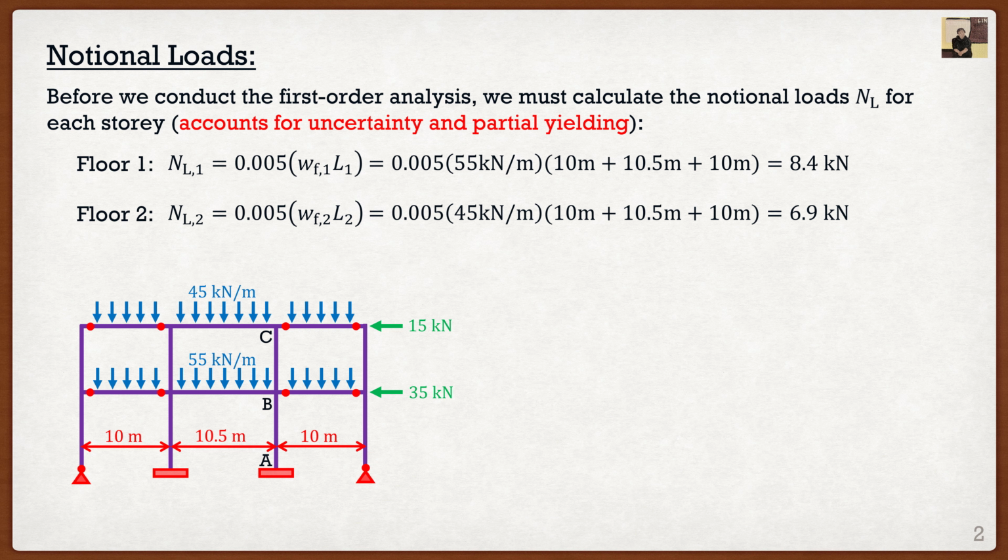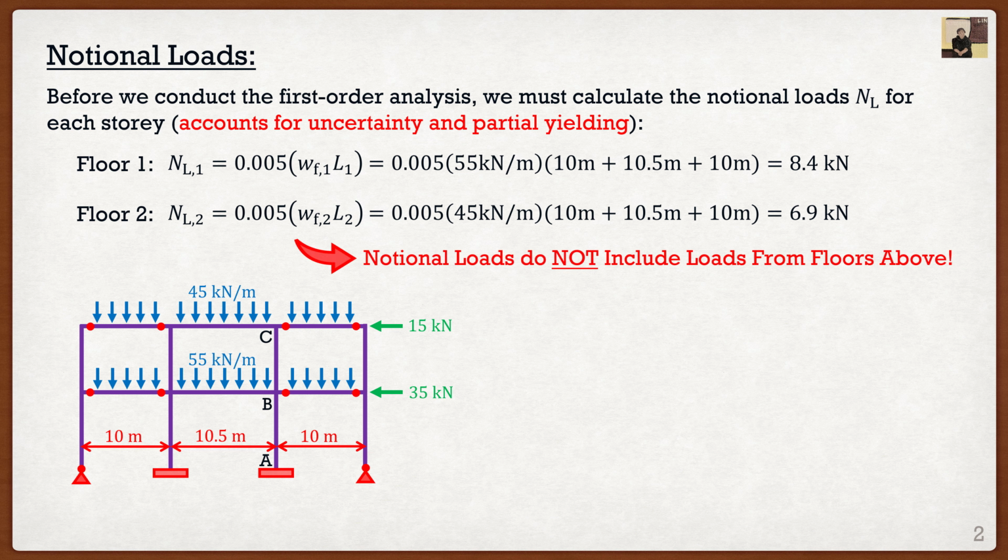And this comes into the first common mistake a lot of students will make. A lot of students, for some reason, like to add the notional load of the first floor to the second floor. For notional loads, we do not include the load from floors above. Now, you're saying, Clayton, of course not. Why would I ever do that?